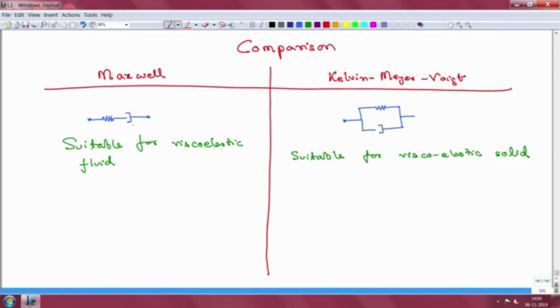It can continue stretching till the strain rate is itself capped or bounded. So, the model for the dashpot only constrains the strain rate rather than the amount of strain. So, when you apply a small amount of force, this dashpot can keep on increasing and increasing, which is representative of a fluid type of behavior, where even if we apply a very small amount of shear stress to a fluid body, it should keep on moving, it should keep on getting displaced.